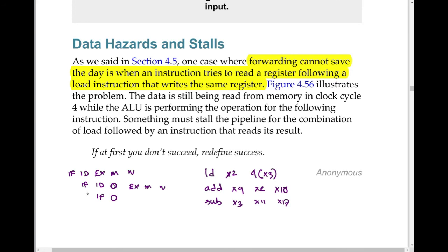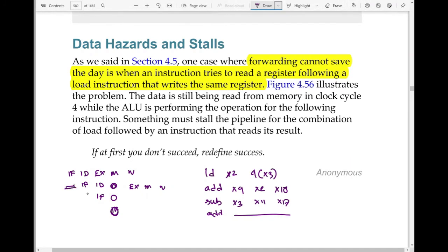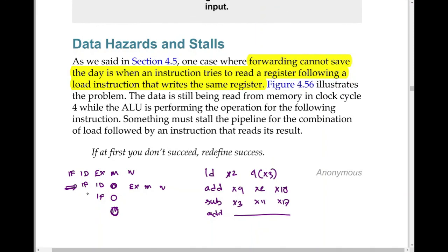But now suppose there is a fourth instruction. Can you fetch it here? This is the question. Because we have stalled this, you cannot fetch an instruction here either. If you stall the instruction in this phase, all the previous modules are stalled as well, because you have stalled the data path in the execution phase, after decode. When you are about to start execution, we need to apply a stall.